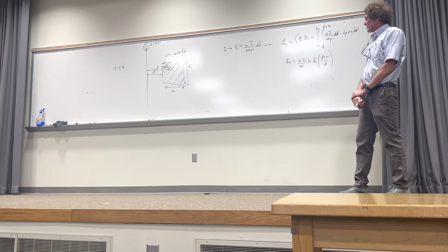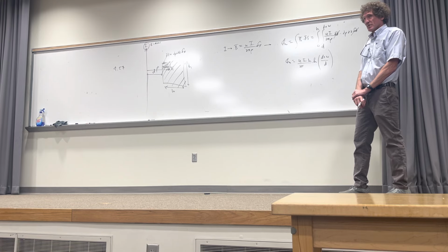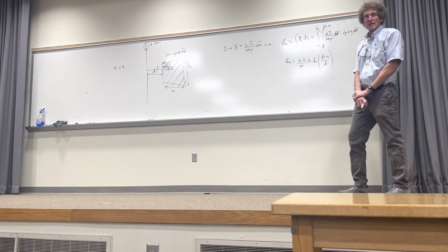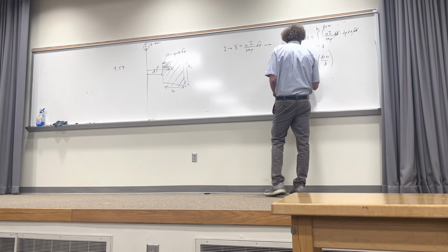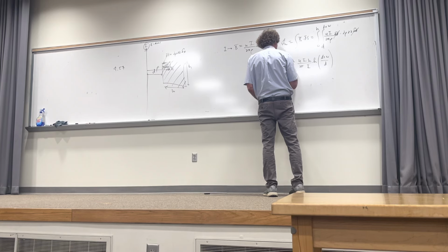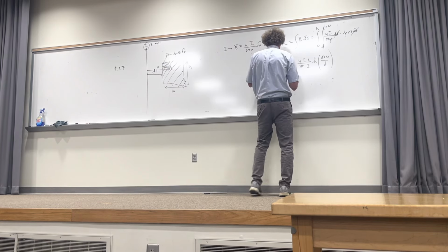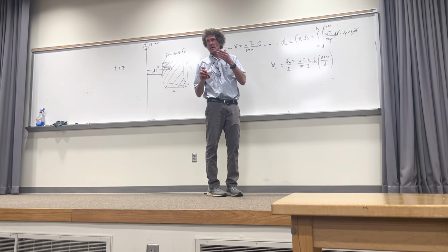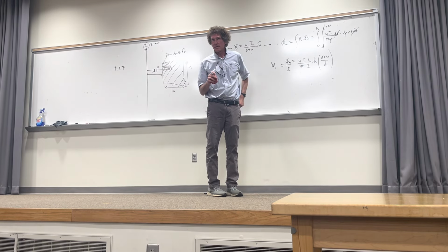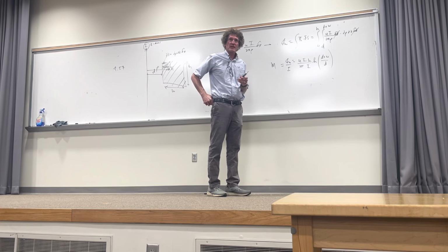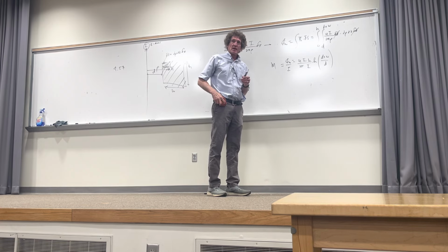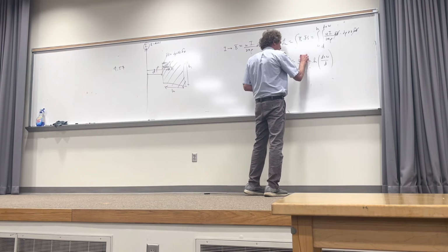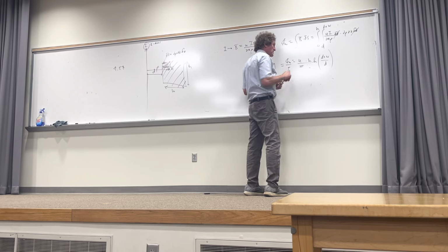Okay, now that's the magnetic flux. What's the last step to get the mutual inductance? Divide current out of it, right? So then I just divide this by current. Then I get the mutual inductance, and I like to put an M there for mutual. I think in his book he used L sub M, but I like M. M is a more classic way of doing it. I think probably when you had Gross, he would use M for mutual and L for self. I like it that way. So that gets rid of this I, and you can plainly see that that's the mutual inductance for one turn of wire.